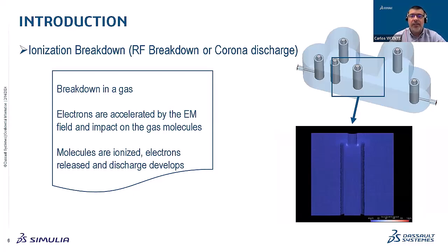This means that more electrons are generated, which can eventually lead to an electron avalanche and then the formation of an electron plasma. The problem again is the degradation of the performance of the component. You can see here in this filter how the electron density is growing at a particular power level close to the tuning screw, and that discharge is being developed.